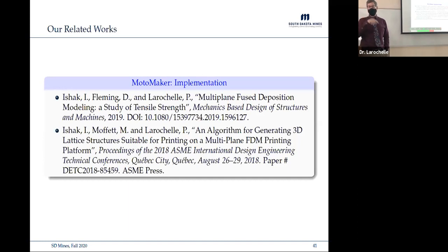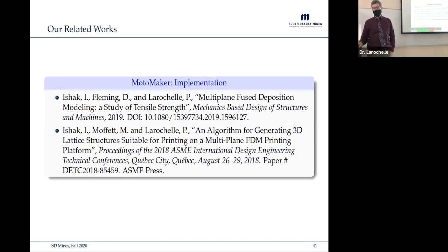The Arduino Mega board actually controlled those, in conjunction with the cooling from the compressed air, to get the temperature we wanted, both at the nozzle as well as outside the nozzle. So we were looking at temperature coming in by the heater in the extruder, and we were also measuring the temperature right outside the nozzle tip, and then controlling that.